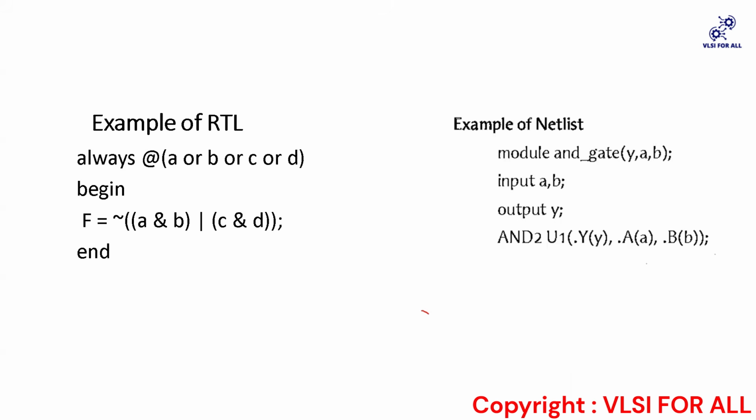Okay, I gave you a quick glimpse of all the topics of synthesis, right? We can further discuss setup and hold violations and how to fix them. HVT and LVT cells, what are those? What is the importance of HVT and LVT cells, and when you need to add or remove those for better performance, and so on.